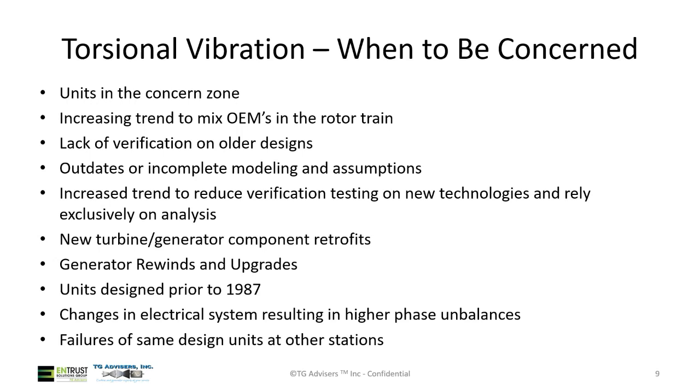There is a trend in the industry to mix OEMs these days, and there's a lot of great OEMs that make a turbine rotor that'll fit into a lot of different packages regardless of OEM. But if you're making big design changes, that can influence where your frequency lies. So you need to do some due diligence and verification around that. Some of the really old units, if you have not had verification of the unit, if you're going through retrofits, you'll want to do that.